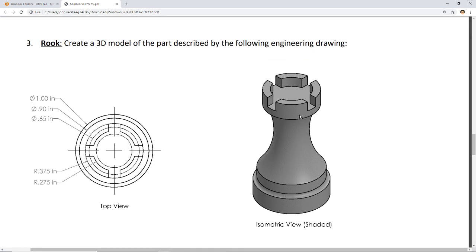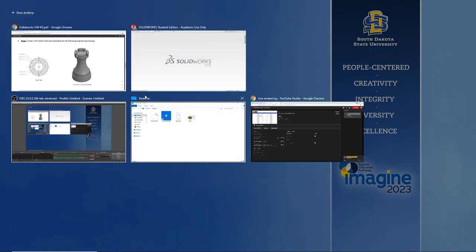This chess rook has rotational symmetry, and then there are these notches at the top of the rook that you have to create. Well, one option would be to create them with a linear cut after you extrude it. Another option would be to extrude the entire shape and then have a linear extrude that extends out of the top of the rook. So, like, real rough approximation here.